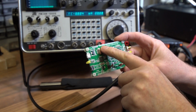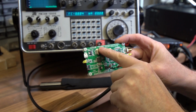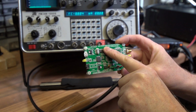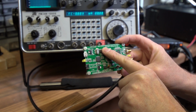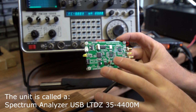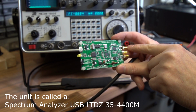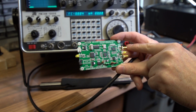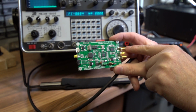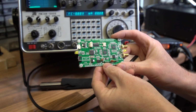This particular one starts at 35 megahertz, like the left point of your screen if you like. It won't see anything lower than that, but it goes up to 4.4 gigahertz, 4,400 megahertz. So it's very high into the microwave band. It's particularly good for VHF, UHF and above, and it also outputs at those frequencies. It'll put out a 0 dBm calibrated output signal, and it's reasonably accurate across the band. I think it's quoted as being within 2 dB or something of that nature, right across the band. So it's not bad at all. Maybe it's even better than that, possibly down to 1 dB.